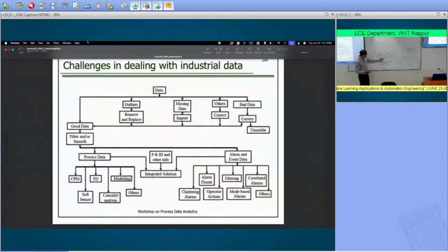When you do that by using all the past values of y, up to y t star, then you have what is called a filtered measurement. You're using all values of y up to the current time, t star. The formal mathematical way of writing this is the expected value of y bar t star, given all your measurements up to y t. Right. So that's the filter.